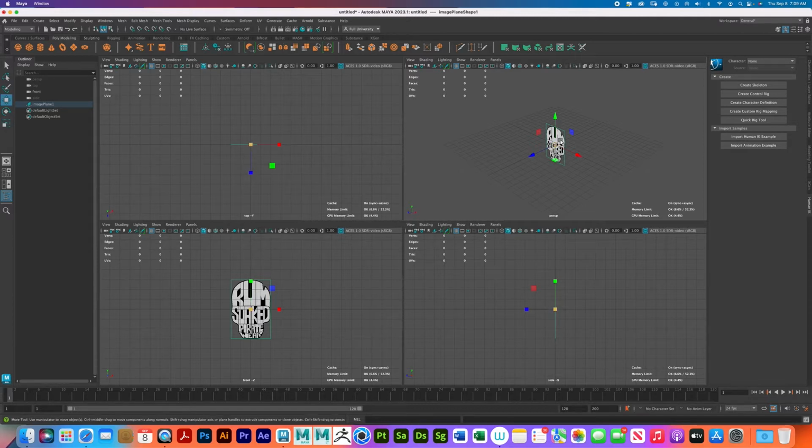I'm going to press W. I'm going to push it towards the back, and you can tell because you see these lines here. If it's back, the grid will cover the design. So I'm going to push it back into space. I do this so that when I rotate, it doesn't interfere with my model. It's going to be very rare that it's going to interfere with what I'm doing in my turnarounds. So once I'm happy with that, since I'm going to be working here, I don't want all these lines from the grid. I'm just going to turn it off right here.